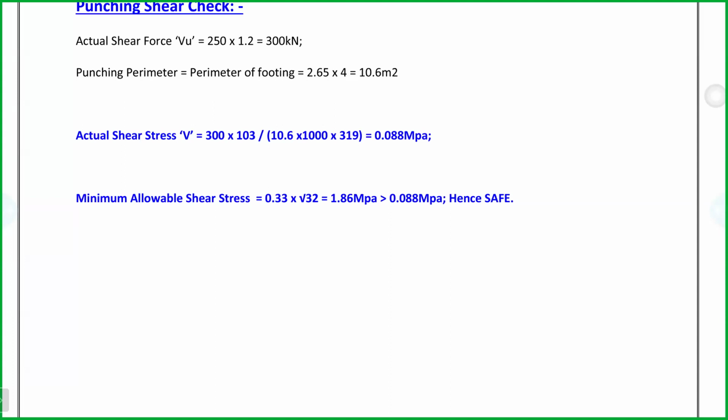I'm talking about center-to-center spacing, center of the rebar to center, not the clear spacing. What is the minimum rebar spacing as per code? It's 2 times the aggregate size. What aggregate size are you using? 20 millimeters, right? So 2 into 20 is 40 millimeters. You cannot use it. Why? The vibrator needle you are using at the side is minimum 40 millimeters.